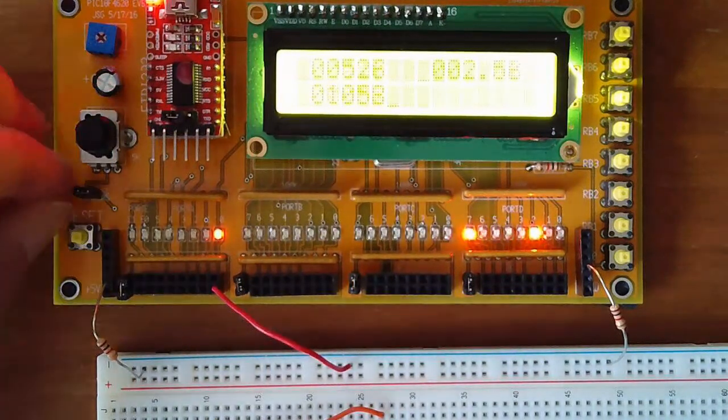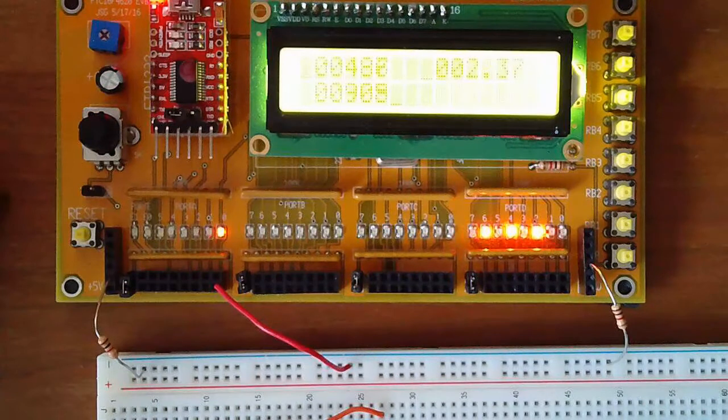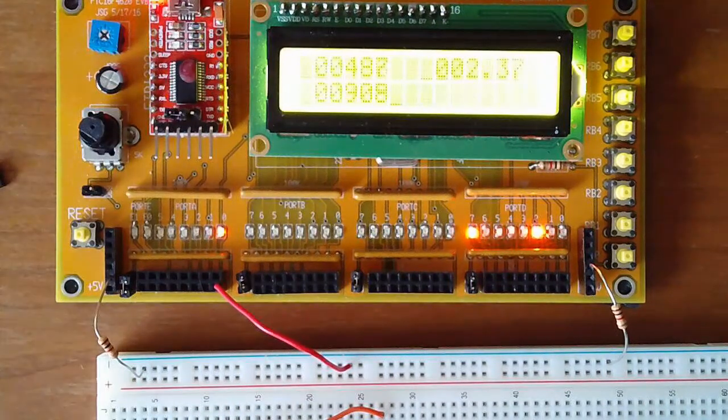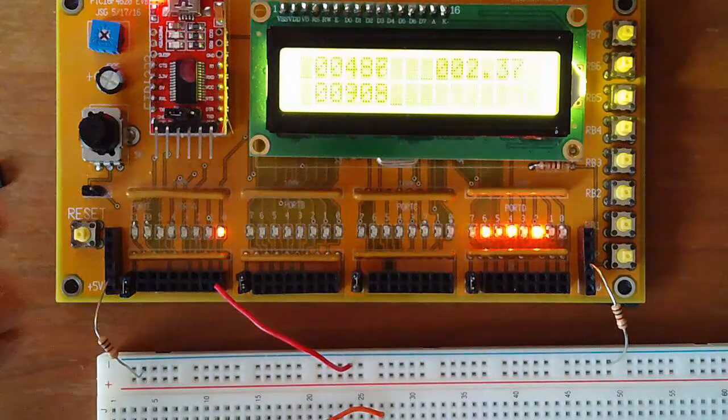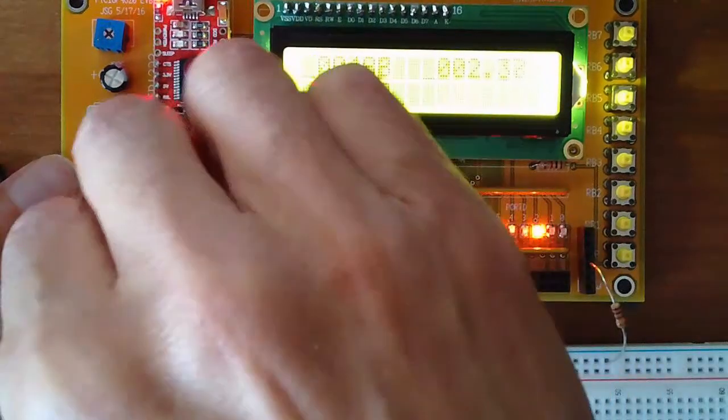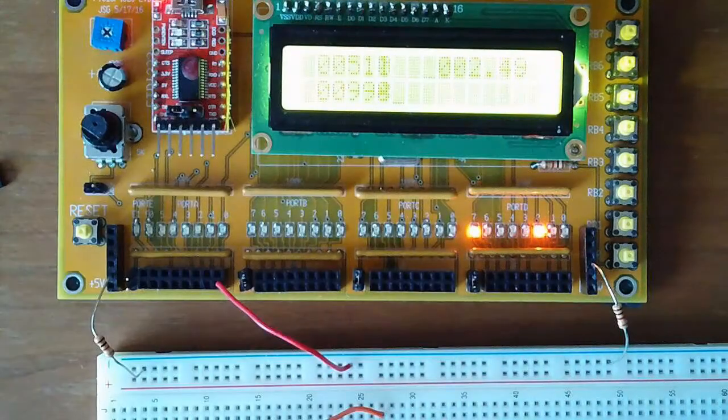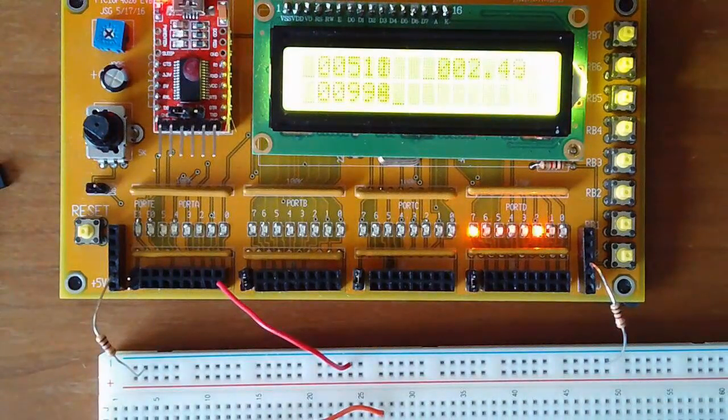If you take this jumper off, that disconnects the pot, and I don't want the pot changing the reading. I also have the LEDs turned on. That draws extra current. That's going to affect the reading. Pull this jumper off. That disconnects the LEDs. They're off, so it's not as pretty. But then I don't have the current over here drawing power. So this says my 1K resistor is actually 998 ohms.